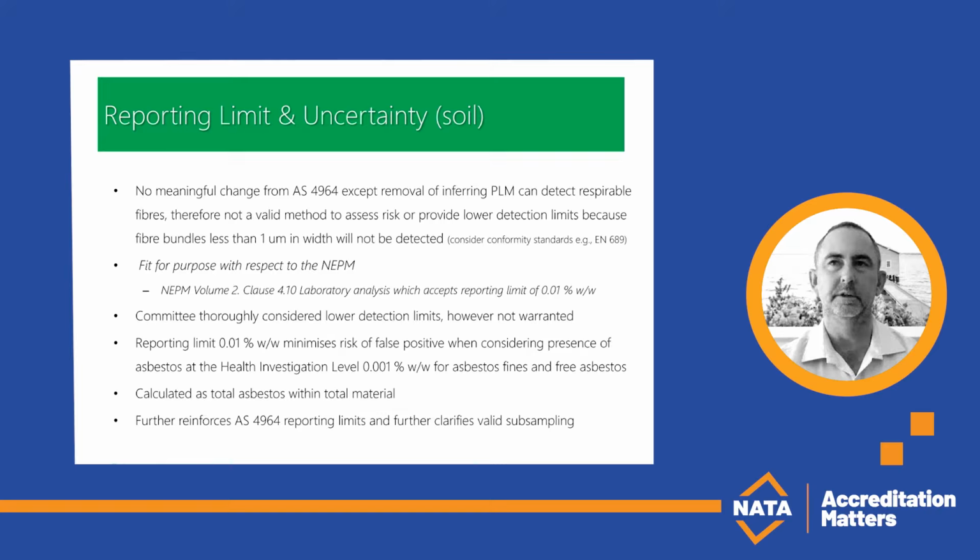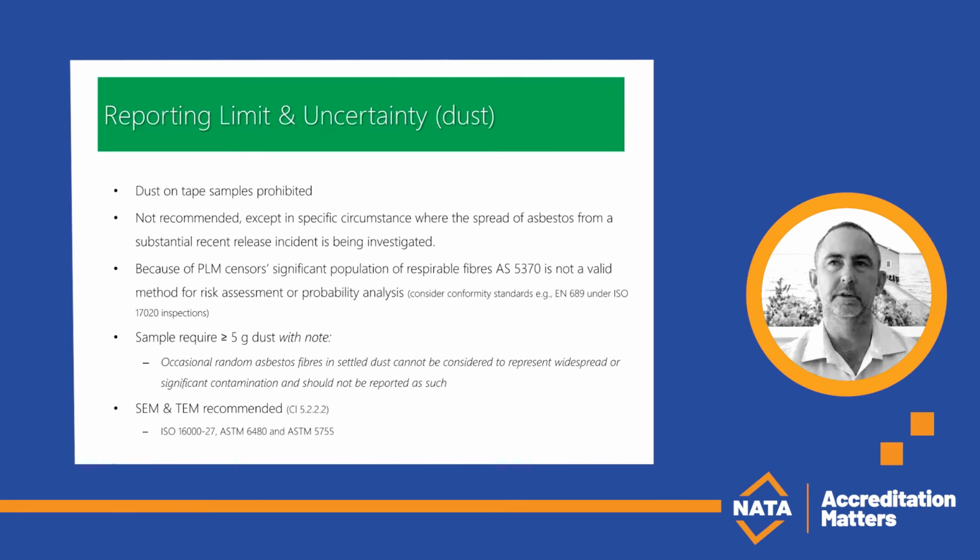And it's important to remember that the NEPM guidelines represent only a health investigation threshold, and that contamination exceeding this level doesn't necessarily mean that the material is unsafe, but indicates a need for further investigation and analysis. When we compare the gravimetric determination with the analytical method, it's generally less common to detect anything above the reporting limit through analytical means alone. And since the health investigation level can be reached through various methods, the analytical result isn't the sole determinant.